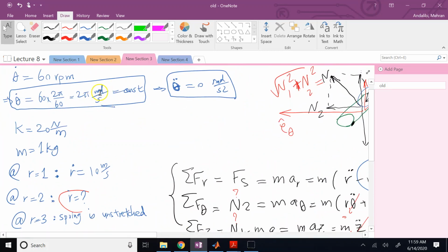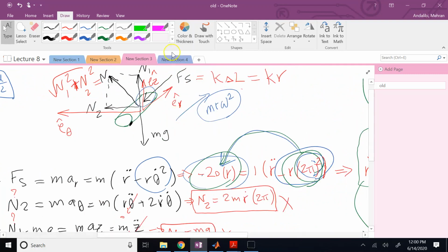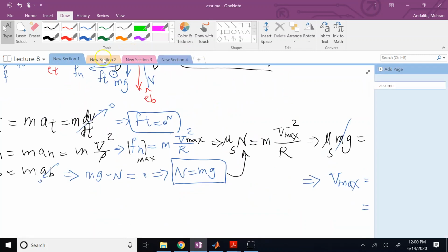So if I want to spin slower, I would expect my r dot to not increase. If I want to rotate too fast, then I have to what? I have to compress the spring back because I'm spinning too fast and I need a lot of force for that to happen, and this spring force is not giving me that. So what should I do? I compress the spring further back and increase what? This delta L, so I now can get a bigger force out of the spring to make the equilibrium happen. But when you increase the length of the spring, what happens? Your radius is getting bigger. Okay, so this is all the stuff behind it.